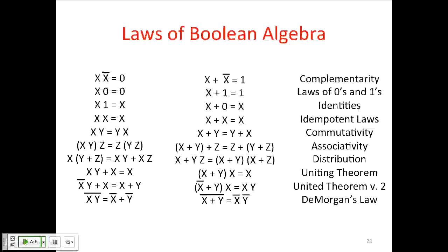Here the inversion is on the output. You AND x and y, and then you invert the result. Here, I invert x, I invert y, and then I AND them. Okay? So if the bar goes across multiple things, you're inverting the whole expression under the bar. And so here I'm inverting each of these variables individually and then combining them with the AND. Okay? That's a logical convention. Any questions on this? I think a few exercises will help hammer home how these work.